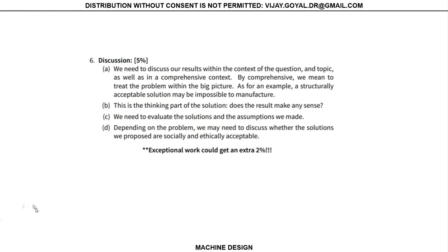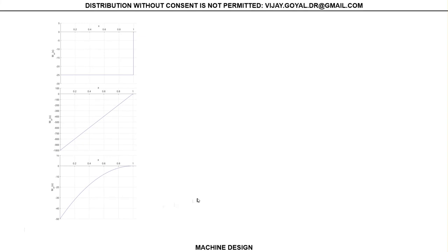For number 6, you want to discuss the answers you have. So the whole purpose of this is basically to find a critical location. We know that this is moment driven, right? The problem is moment driven. There's rarely axial loads or shear driven. So your critical location will be the location where your moments are maximum. In this particular case, it's crystal clear that all your moments are maximum right here at x equal to 0. Okay, so they're right here.